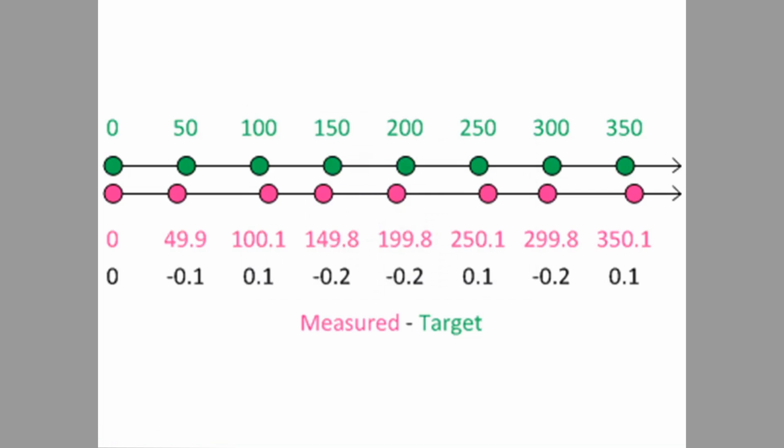Some samples have been provided in the zip file that comes along with these videos. And then the laser is going to give us numbers, and usually this will have to come out of the metrology software somewhere, but we're just going to read them off the screen. We move to 0 millimeter, we zero the laser out. We move to 50 millimeter, the laser tells us we went to 49.9. We moved to 100, the laser tells us we moved to 100.1, and so on down the line.